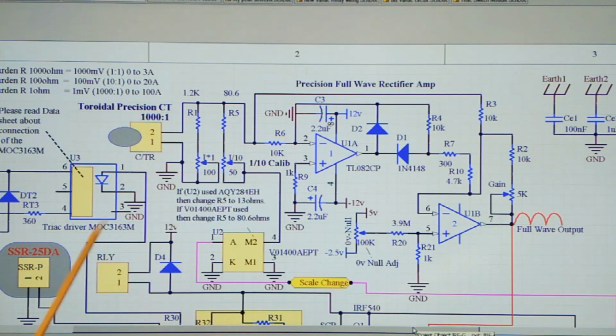But because I wanted to be fussy, if I hook up a true RMS meter, I wanted to read the exact input of the primary on the secondary there. That is why it ended up being a bit higher than 1K, because the transformer would probably still have some errors regarding the windings and the core.